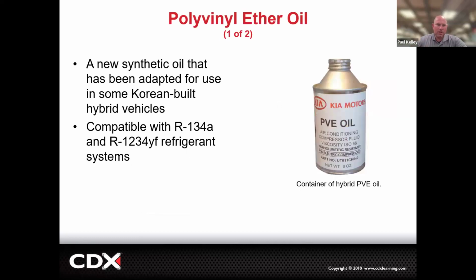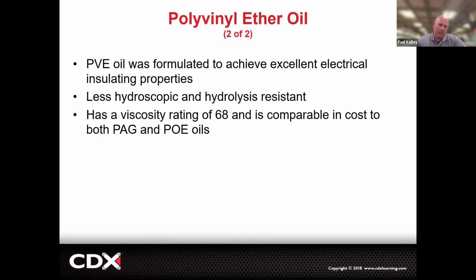And here's your polyvinyl ester oil. And then again, compatible with R134A, R1234yf. This is compatible with potentially both. And we're seeing this on some of the Korean vehicles more so. And it's a good one for electrical insulating.